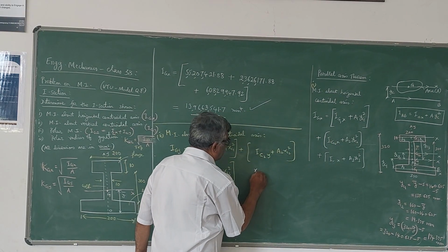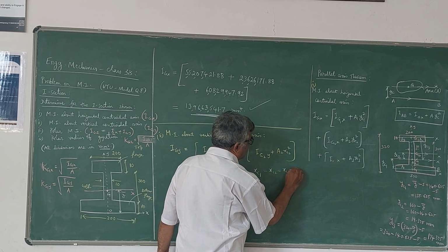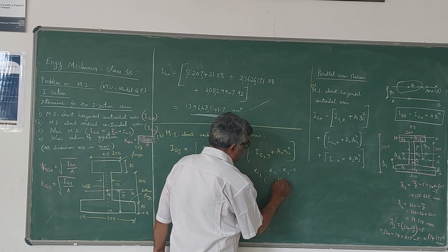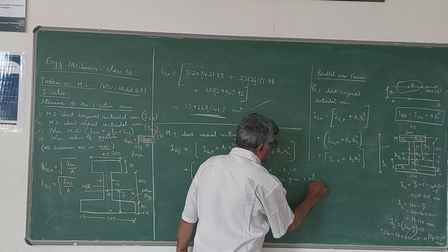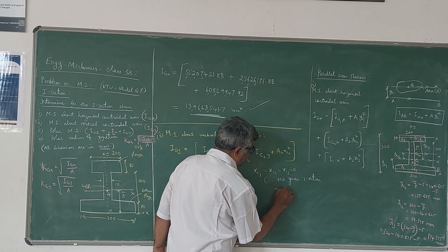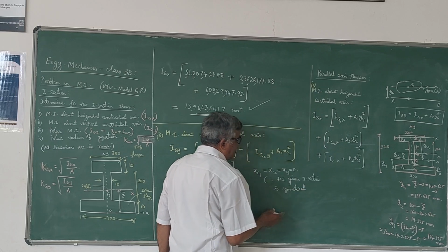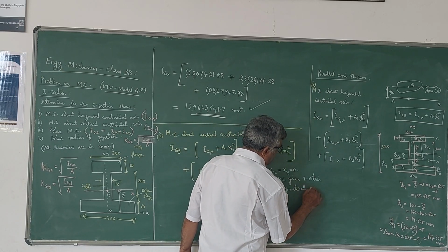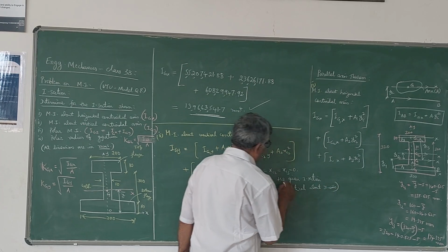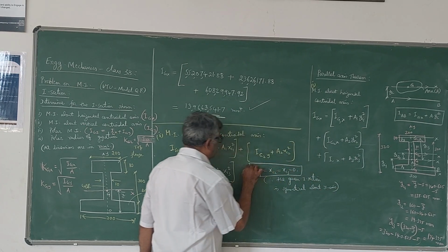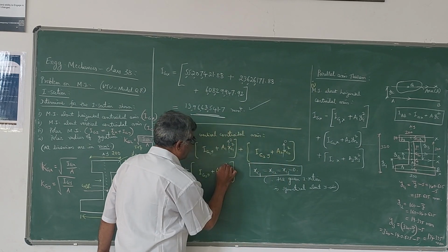So in this problem, xe1, xe2, xe3, all these three will be zero because the given I section is symmetrical about y-axis. This is very important. Any figure if it is symmetrical about x-axis, ye1, ye2, ye3 will be zero. Here, since it is symmetrical about y-axis, all these horizontal distances become zero. That means this term becomes zero, this term becomes zero, this term becomes zero.